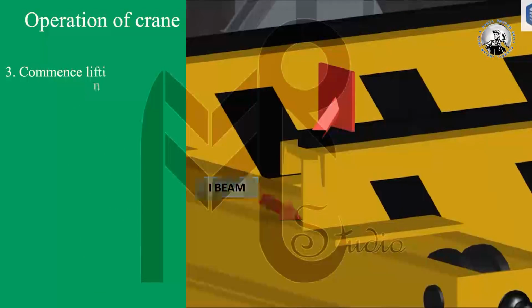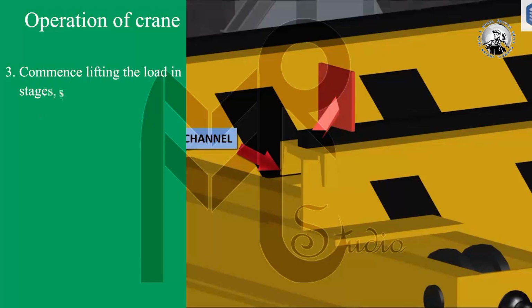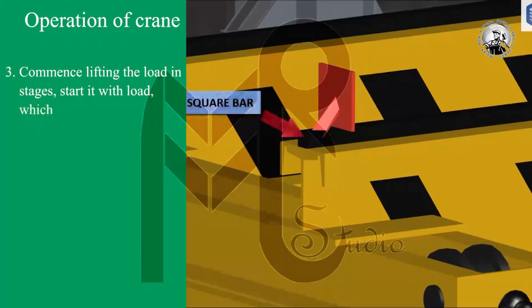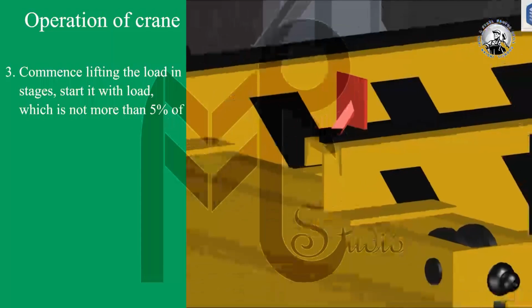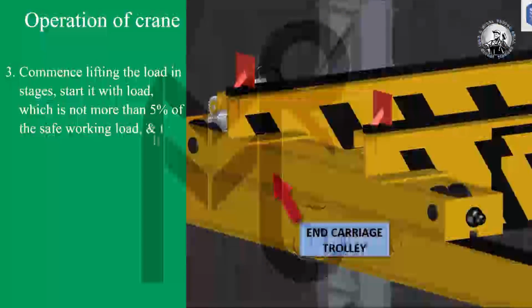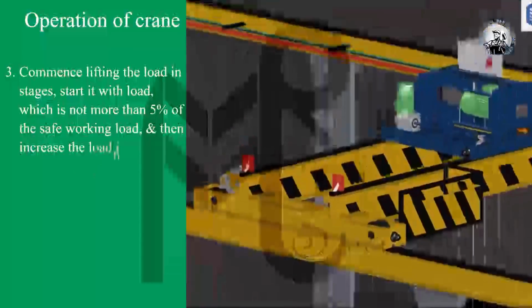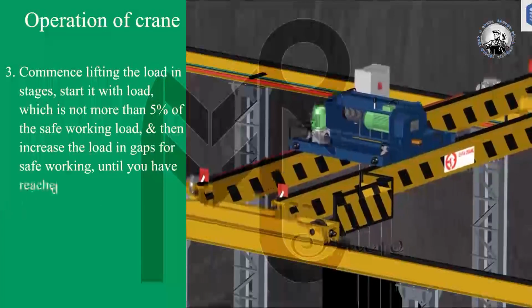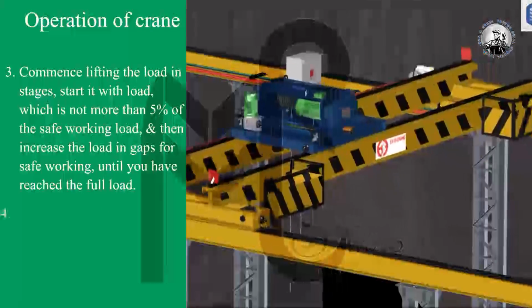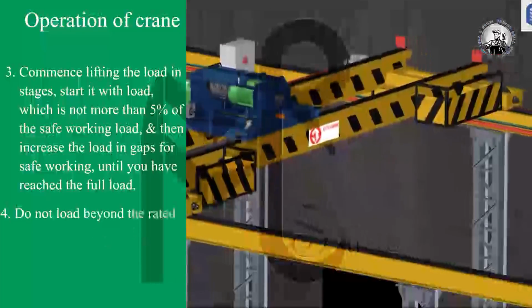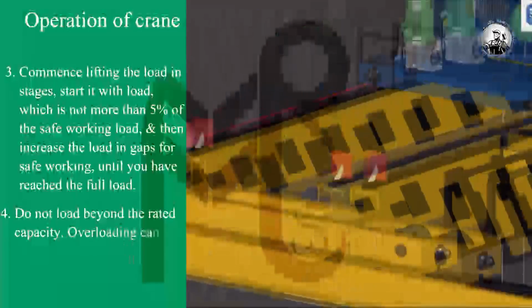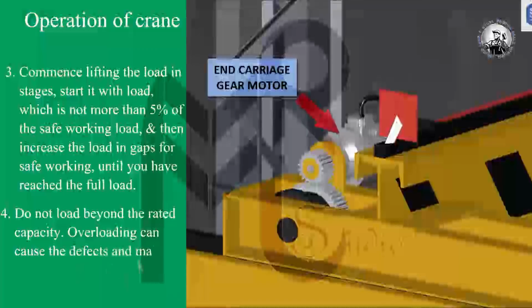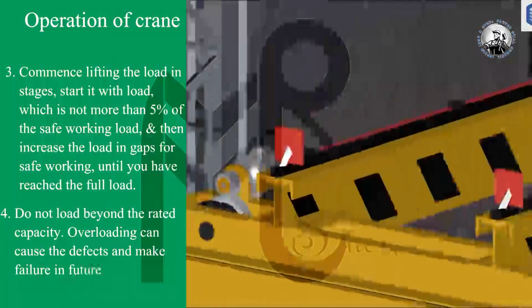Commence lifting the load in stages. Start with a load which is not more than 5% of the safe working load, and then increase the load in gaps for safe working until you have reached the full load. Do not load beyond the rated capacity. Overloading can cause defects and make failure in future.